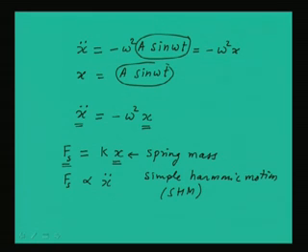Sometimes it is advantageous to represent the harmonic motion in the form of a vector which is rotating about a point. Especially when we express the vector in the exponential form, we get a mathematical advantage: the expressions we will be handling in the analysis of vibration become simpler, and even the mathematical operations on the exponential form of the terms are simpler. So, let us see how we can express the harmonic motion in a vector form.